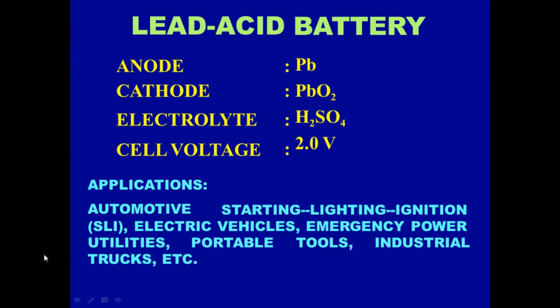It is the most important part of the lead acid battery, which separates the positive and negative plates from each other and prevents the short circuit. The separator must be porous so that the electrolyte may circulate between the plates. The separator must have high insulating resistance and mechanical strength. The materials used for separators are wood, rubber, glass, etc. And we can also use PVC.